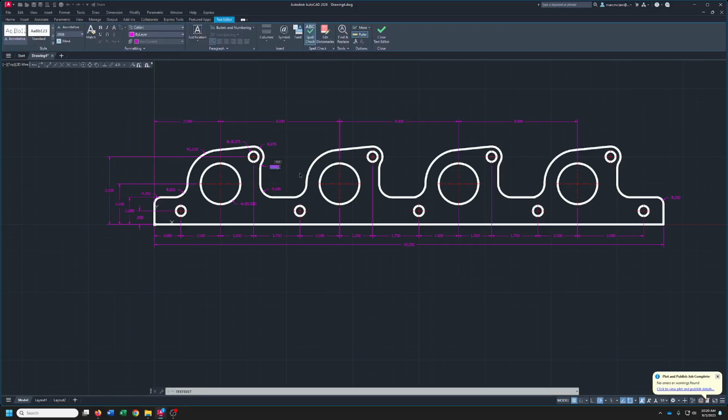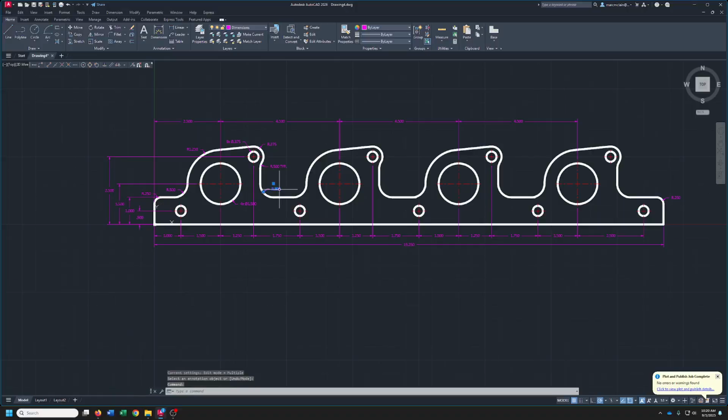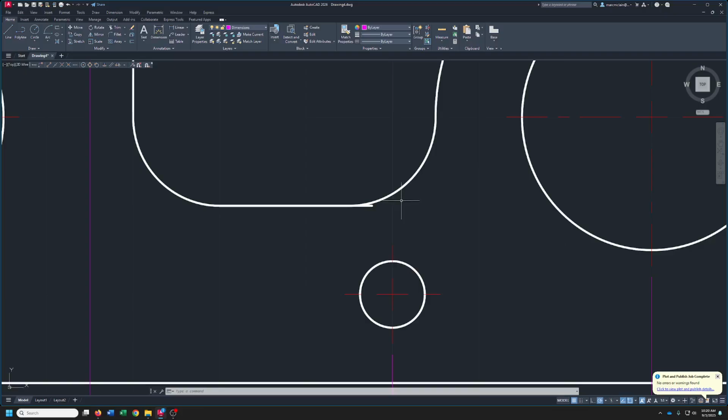End, space, capital TYP, period. Now, I can remove that one and that one. See how that saves space? So we know that each one of these, that's what the TYP means, each one of these is going to be 0.5, so I don't have to go back and mark every single one.